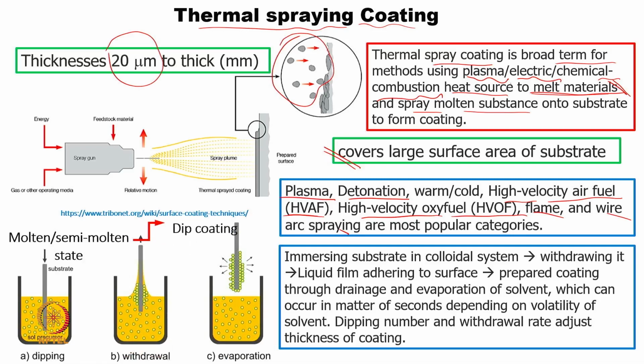Now, there is a very simple dip coating which is again cost effective. What we do is a kind of gel coating. In this case, there is a substrate which is dipped into the solution, with whatever precursors we are using here, and then it is withdrawn. We can find that some liquid gets deposited on the surface. Now, the person who has a good knowledge will know how many seconds or how many minutes we need to keep it in the air. So, the deposition happens, and then it is inserted back again to increase the deposition thickness as such. So, this is what a simple one is.